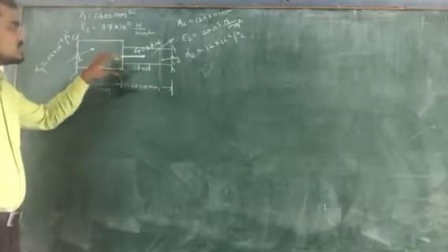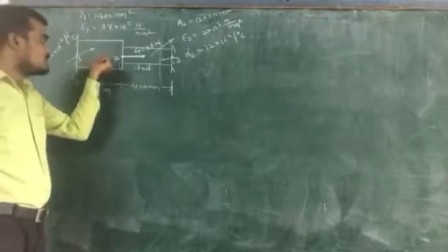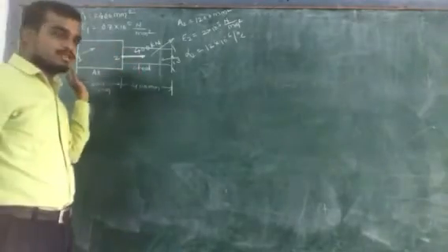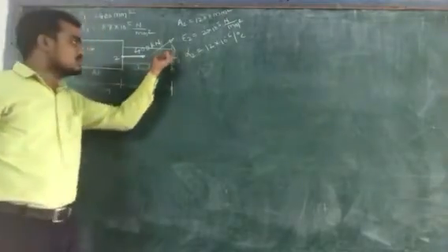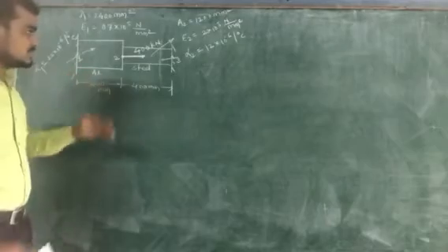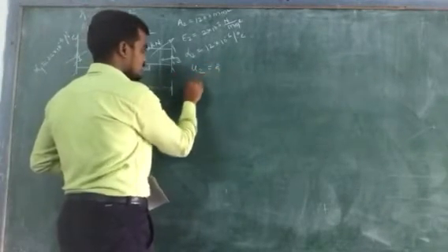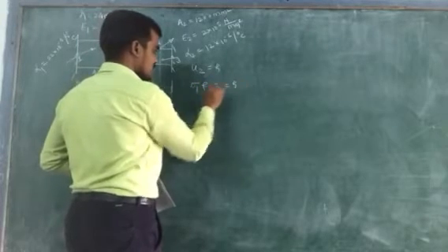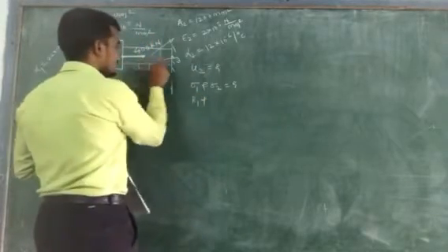Then also find the stresses in each element, the stress in the aluminium bar as well as the stress in the steel bar. And next, find the support reactions, at the left side as well as the right-hand side, because these two ends are fixed. So these are the terms: first find U2, then find sigma 1 and sigma 2, and finally the reactions R1 and R3.